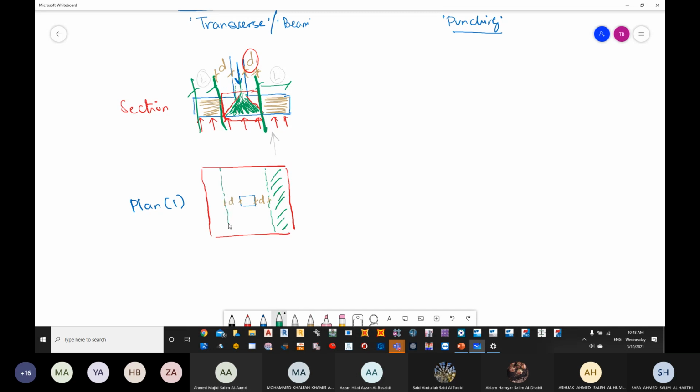Now of course, if the foundation is not symmetrical, as we have illustrated for the bending moment, you have two lengths, and then of course you will be taking the higher length of the two. So for example, if this is my L1 and this is my L2, if both of them are the same, then it's fine. If L1 is bigger than L2, then I'll take L1.